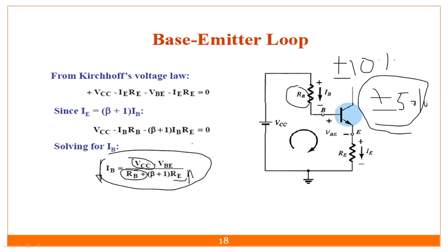To make the circuit very stable, we have to make the circuit not depend on a single quantity, that is not only on RB, it should also depend on RE. So even if this changes, by maintaining this value of RE, the circuit will be more and more stable. So IB is equal to VCC minus VB divided by RB plus (1 plus beta) RE.